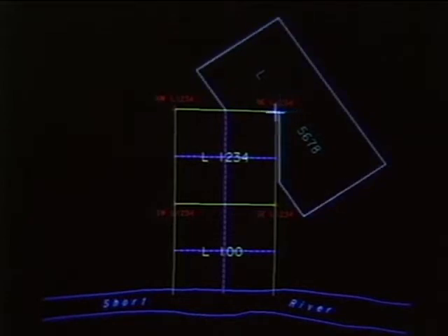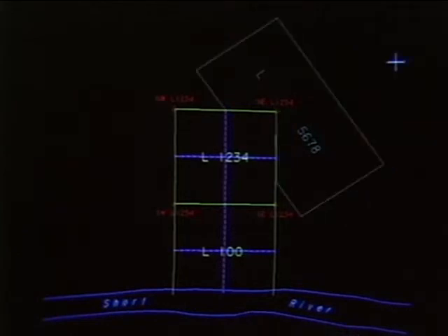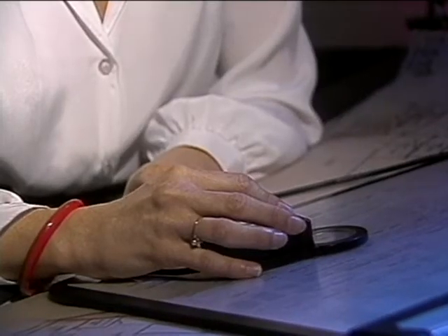The mapping software gives the operator the ability to rapidly and easily adjust errors. Once an error has been adjusted in any given chain of survey lines, the operator can proceed to build other parcels out from it until she's coordinated all the cadastral corners on the map sheet and digitized any natural boundaries.